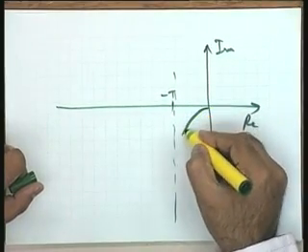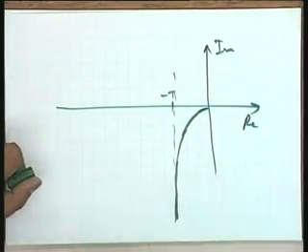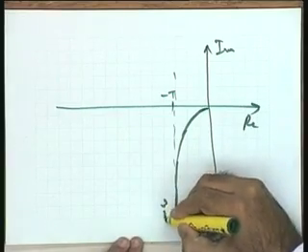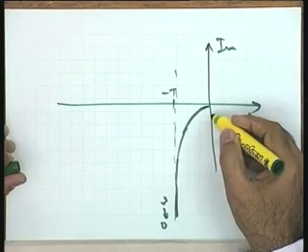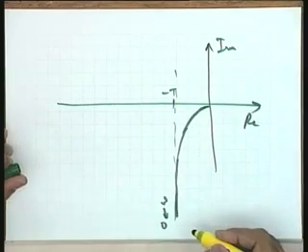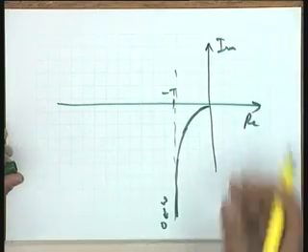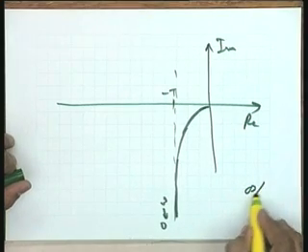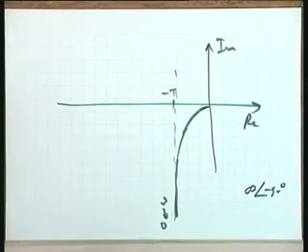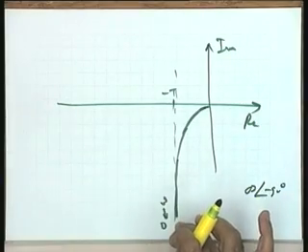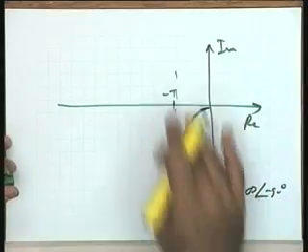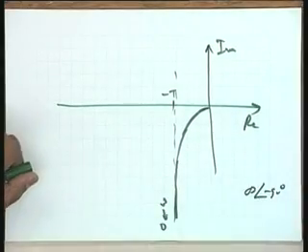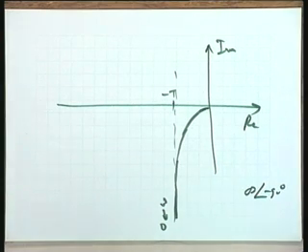You see that this is the plot, this is the only information I want to give. This is omega tends to 0. Omega tends to 0 is a line which is tangential to this particular line, the minus t line, which now you can see is equivalent to saying that it is infinity angle minus 90 degrees. The two informations are the same. The only thing is that this is a more complete information. It is not tangential to this axis, rather it is tangential to the axis drawn at the minus t, 0 line. Is it alright please? I hope this point is clear.